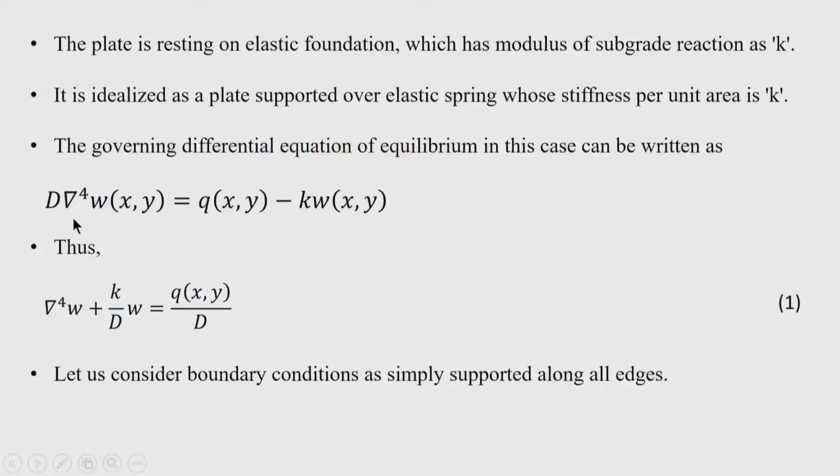So, this biharmonic operator I have explained to you earlier, and after expanding we can write this differential equation with all the terms. Thus del 4 W plus K by D into W is equal to Q x y divided by D.